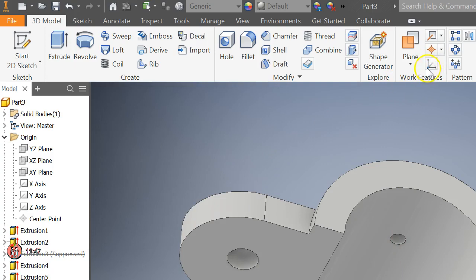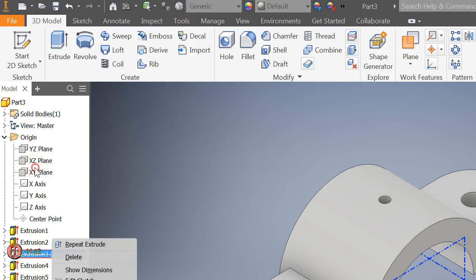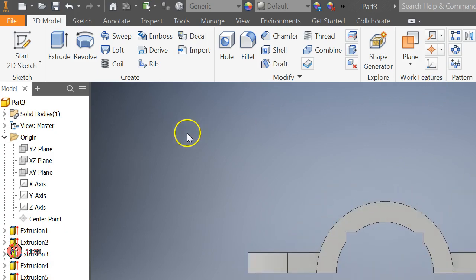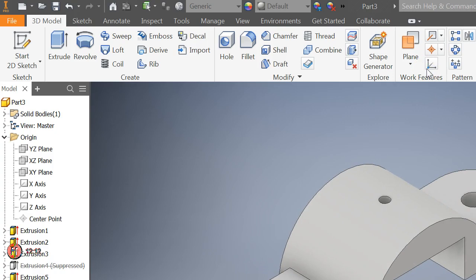So now I've got my object, and I've got a half round cut in it. If I turn this back on, unsuppress, then I do have something a little weird. It's like a cat with ears or something. If I try to suppress that one, then I'm probably suppressing my hole as well. No, I didn't. Okay. I guess because the half round was done first and then the hole. So you see, I've got either one that I could go back to, all within the same drawing.